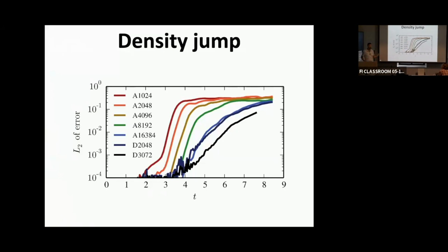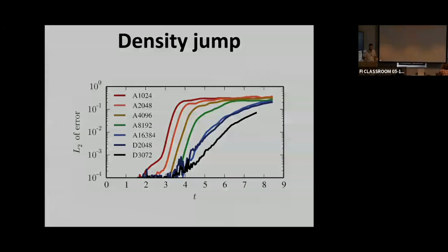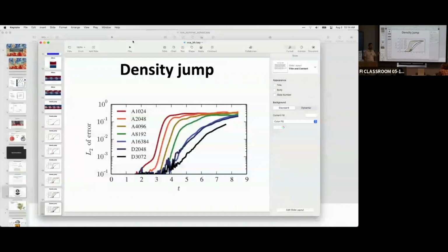But if you're doing a low Mach number problem that should have a smooth solution, the accuracy per degree of freedom is much higher for the high order spectral code. So you can get the same accuracy at much lower resolution. That's the regime where these codes are faster overall in time to solution: when you ask how much work I need to do to achieve a certain amount of accuracy, not a certain amount of resolution, which isn't necessarily a good proxy here.